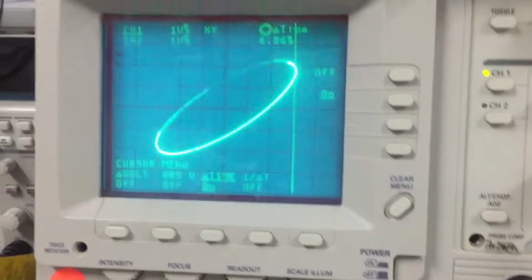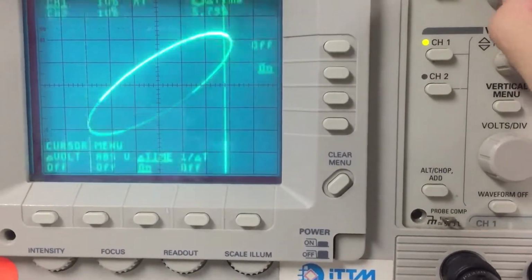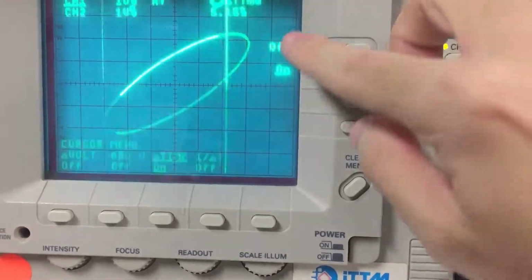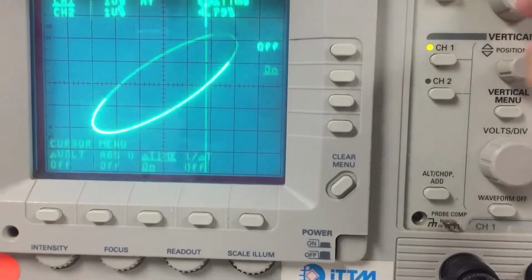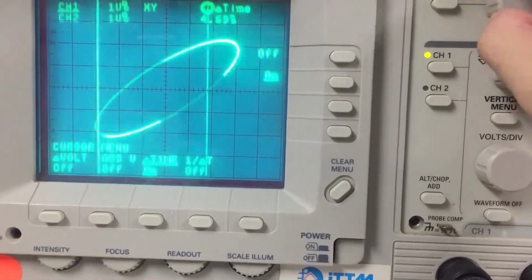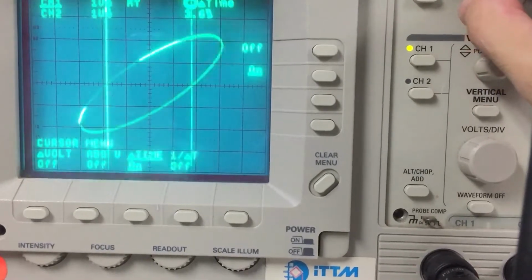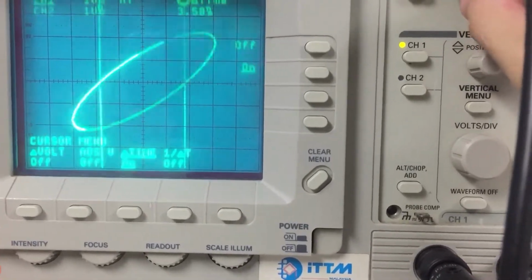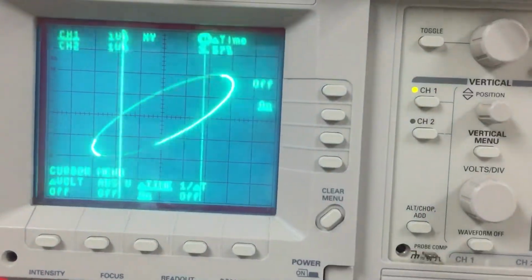Now we want to measure VS0. So for VS0, we just toggle it to the x-axis where it crosses, and then toggle to another vertical line, and then to the cross section. So this is the value, 3.57 volt.